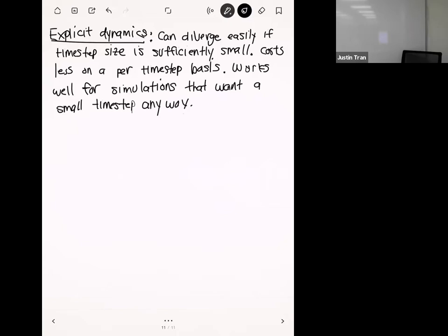You're asking if we can put it anywhere else, and it kind of makes sense that those hold the whole thing. I think it makes sense personally to just put it on the bottom faces. It's not going to be moving. If it's fixed on the bottom faces, both of those are touching the ground, so there's no way it's going to translate. You're right.